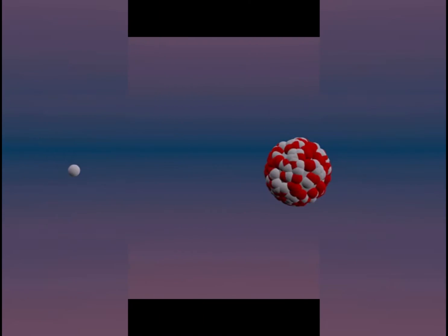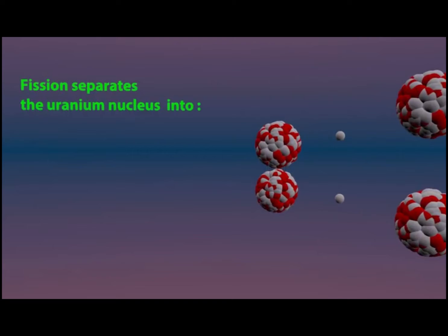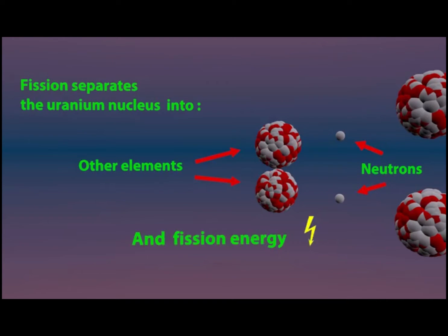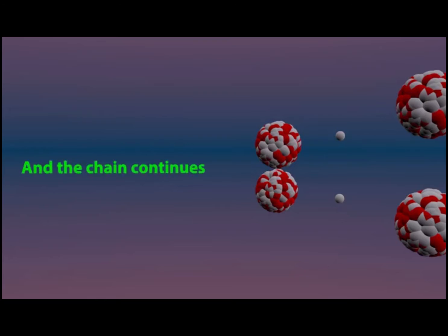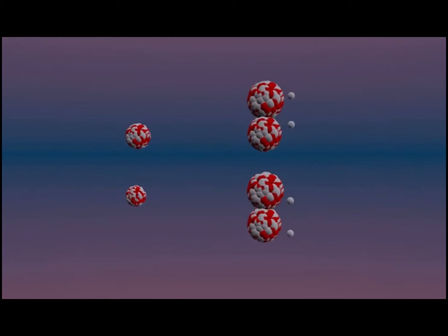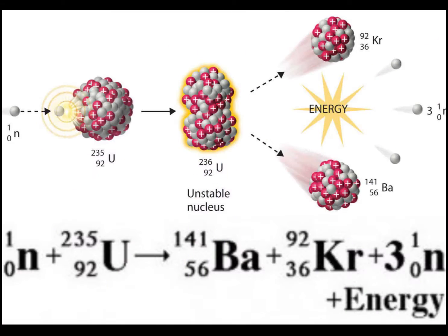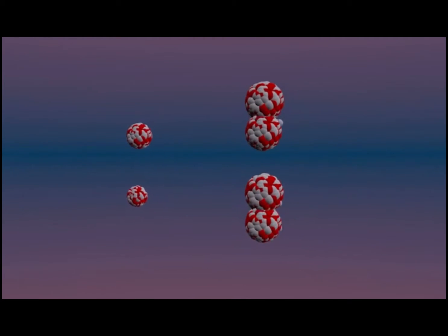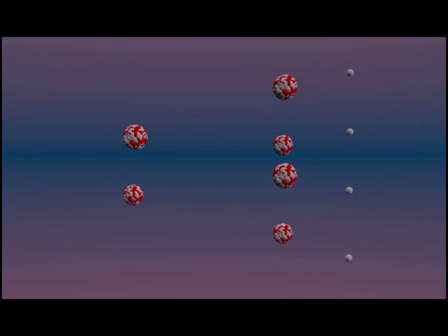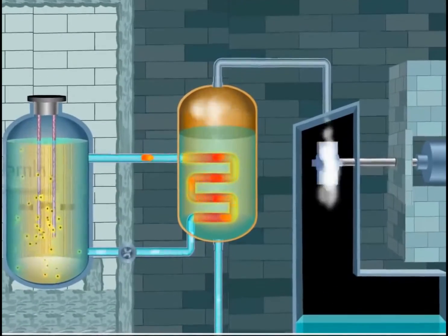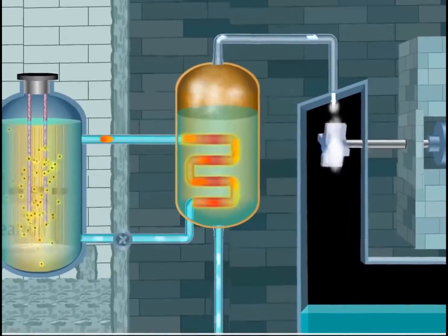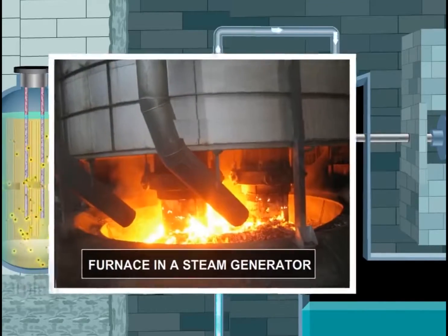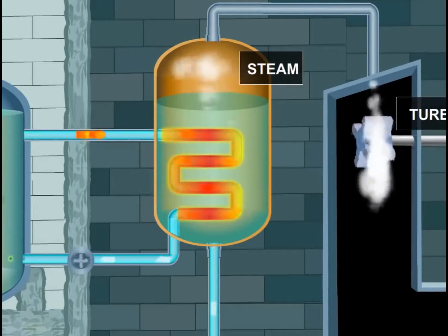By bombardment with neutrons, it splits into relatively stable atoms, releasing an enormous amount of energy and neutrons. The reaction of uranium-235 can be written as: the neutrons emitted are used to catalyze other fuel rods to increase the reactivity when required, and the energy released is used to heat water to steam, which then goes to the turbine to generate electricity.